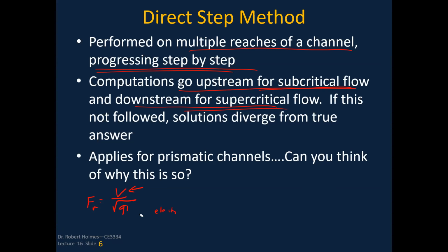Right, as those arrows keep plaguing me. So this is the velocity of a celerity wave. If I drop a pebble in a brook where the water is flowing along, if it's subcritical flow, this still has the ability to emanate upstream, or translate the disturbance upstream, because the velocity is not fast enough to keep it from doing that.